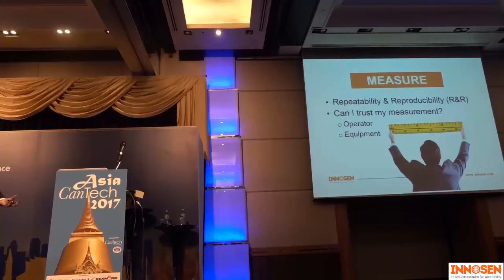Then there's a statistical method on how to add these two together, and then you have the total error for your measurement system. What you now do is you compare that error that you've got with your measurement system with the precision by which you want to control your process. So for example, in coating terms, just imagine that my total error is, say, 2 grams per square meter, but I want to control my process to 1 gram per square meter. It's quite understandable, I'll never get there. I cannot control a 1 gram process with a gauge that has a 2 gram fault.